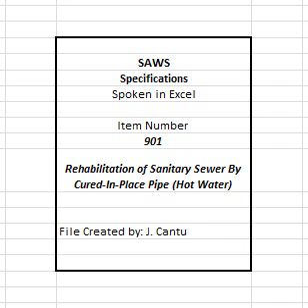1. Water inversion, where the lining is inverted under the pressure of water, and cured by circulating hot water. 2. Winched insertion, where the lining is winched into place and inflated against the sewer wall by either a removable bladder inverted into the lining under the pressure of water or a pre-positioned bladder, which is simply inflated. Curing is accomplished using circulated hot water.